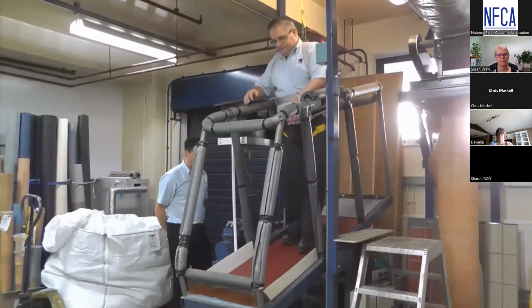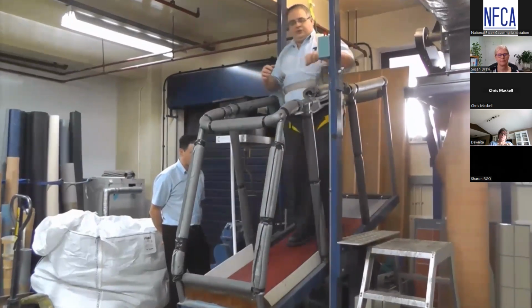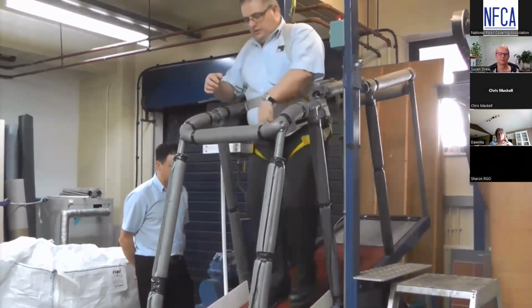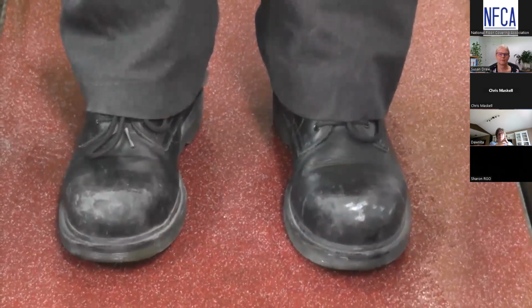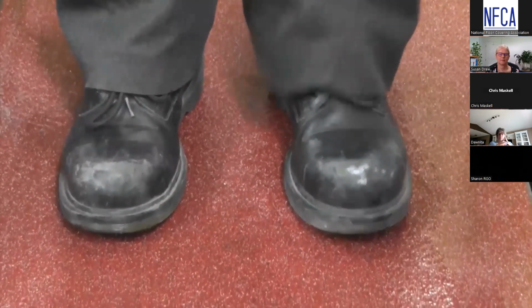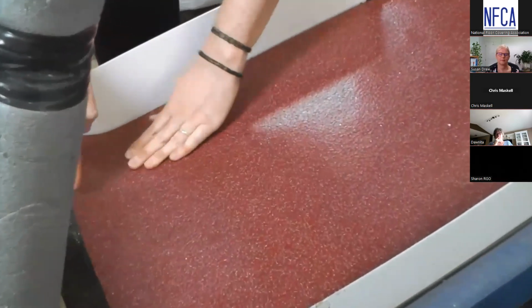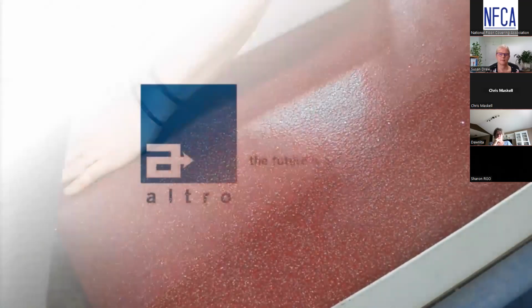One of the benefits of the ramp test is that it uses a person to measure slip. All the other tests rely on machines. However, the shoe used in this test is a safety boot with a heavily cleated sole, which is not representative of general everyday footwear. Another limitation is that the contaminant is motor oil. Most slips occur with water. Finally, this can only test small sections of ex-factory flooring rather than monitoring how slip resistance changes over time with use in real life.